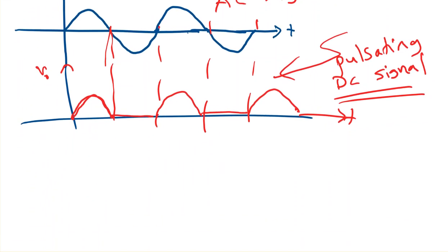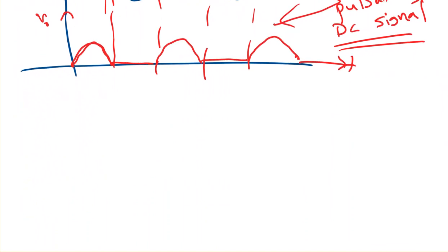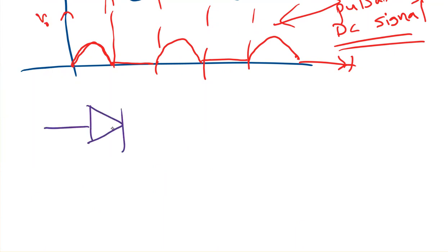In practice, first of all, we'd like to say that this is not exactly the way it should be, which means that I know that in practice, the voltage for the diode will not be conducting unless the voltage is greater than 0.7. And therefore, if you need a real practical case for the output voltage, it will look something like this here, and then the same thing, and then here the same, and so on. So practically, we expect a little bit of variation, but we may just ignore it because it's not that much as compared to the voltage that we will be having.